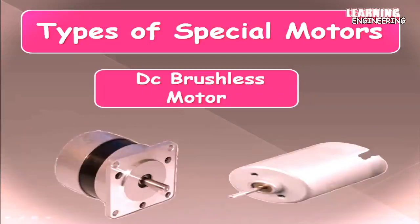DC brushless motors. Brushless DC electric motors, also known as electronically commutated motors, are synchronous motors that are powered by a DC electric source through an integrated inverter or switching power supply, which produces an AC electric signal to drive the motor. In this context, AC, alternating current, does not imply a sinusoidal waveform, but rather a bidirectional current with no restriction on waveform. Additional sensors and electronics control the inverter output amplitude, waveform and frequency.